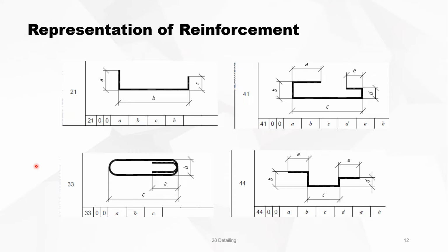And in a bending schedule, you indicate the shape by a small representation. You don't really show the radius here. The dimensions are always outside dimensions, A, B, and C. So shape 21, that's where shape 21 is coming from. And then here comes the number A, B, C. And so it goes on. For each shape, you can have some numbers in it.